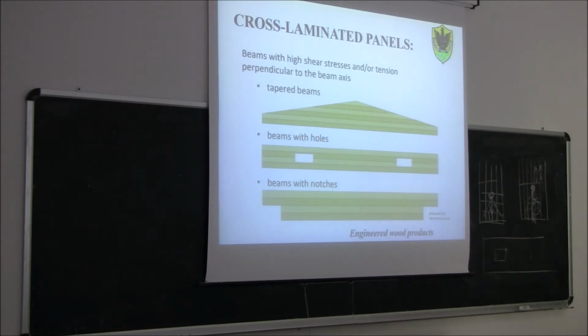Never goes to infinite, of course, but this means that it's very easy here that a crack will form. And then as the load increases, this crack is going to progress. And of course, this crack is not very nice to have, because it's going to separate the beam into portions. So when you do, for example, a bending verification, you assume that here you have only one piece of wood, only one cross section.